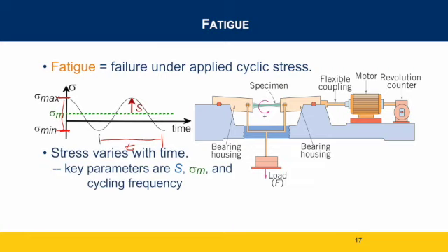So it might take maybe a couple of months to test a heart valve that would last for several years in a patient. That's what fatigue testing is useful for: once you understand the maximum and minimum stresses, you can adjust the time to increase the rate and test materials more rapidly.